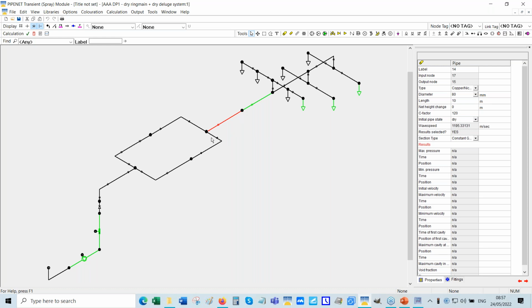Because the water flows at a high rate, because the diameters are big, and the air gets expelled, the water reaches here, and then suddenly it decelerates. So it could lead to a high pressure surge at that point in time. So you've got to watch out for things like that. Okay.